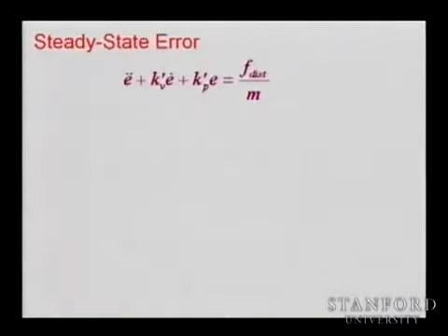So let's see what is going to happen to your errors. I'm not sure how many of you know what we mean by steady state error. What is a steady state error here? What do we mean by steady state error? Yes? Reaching equilibrium, velocity, what its position here is going to be. So steady state is when the acceleration stops, the velocity stops, and you reach that position, but you are not reaching it exactly. There is a small error. So it's like a spring mass system. If you apply a little bit of perturbation with an external force, it's not going to go to its rest position. It will be very close, but not there. And that would be the steady state error.